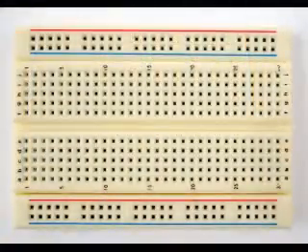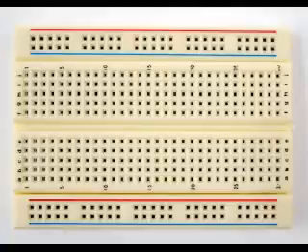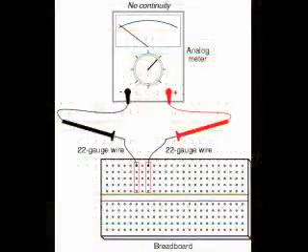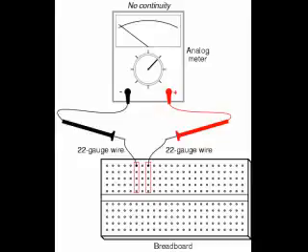This breadboard or protoboard has two common connection rows along the top and two common connection rows along the bottom for positive and negative power supply connections. Conversely, on this breadboard, points within a row of 5 holes vertically in this illustration are not electrically common because there is no continuity between them. Continuity describes what is between the points of contact, while commonality describes how the points themselves relate to each other, though those little 5-hole groups are not connected.